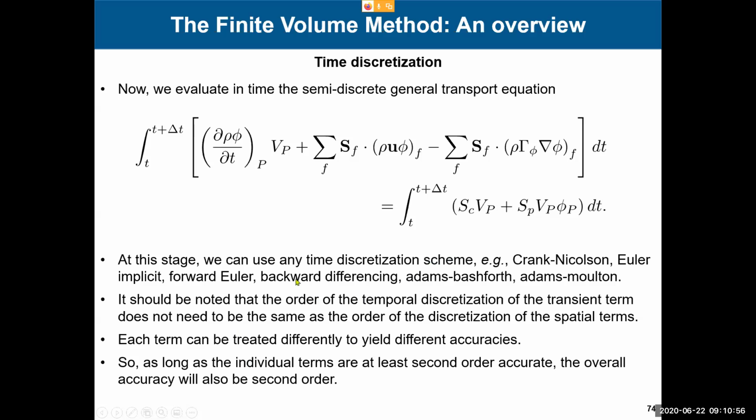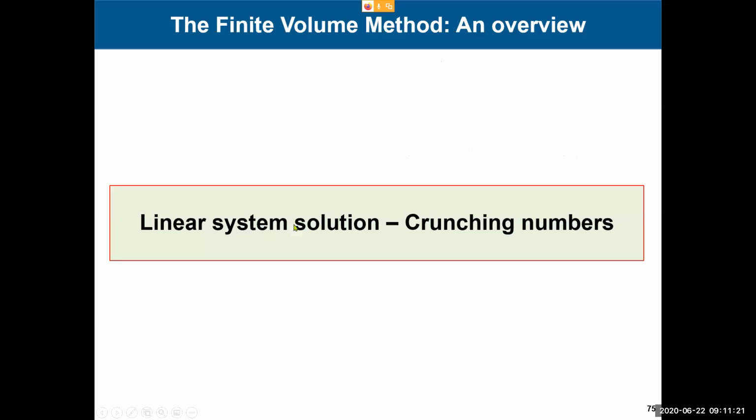One thing here is that diffusion also applies in time. So talking about first order approximation, second order approximation is important. However, it's less severe. In time you can get your way around using first order discretization with no problem, but have in mind that you need to keep your CFL less than 2, ideally less than 1. But you can do it and you can get the same accuracy, okay?